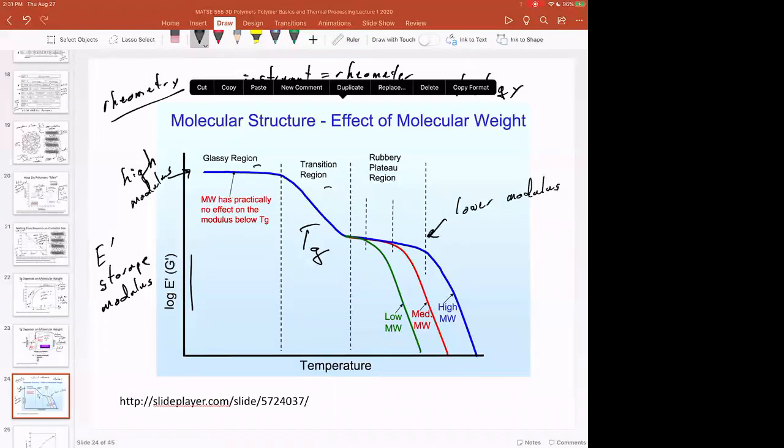And so rubbers are really interesting materials because you can have a really soft rubber like a rubber band, or you can have a really hard rubber like a car tire, or you can even have harder rubbers than that. And so there is no one modulus that we say defines a rubber. Rubbery materials are defined over a range of moduli. And we'll get familiar with a bunch of different rubbery materials that are useful in additive manufacturing.